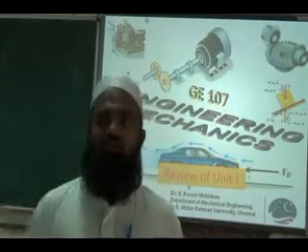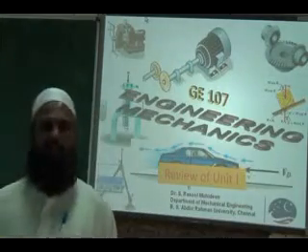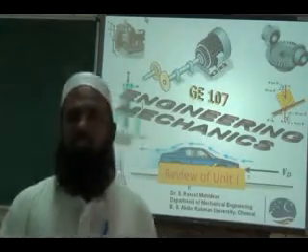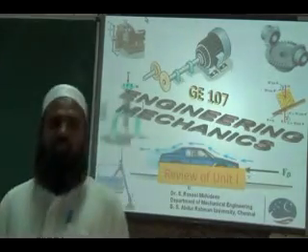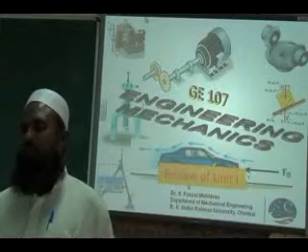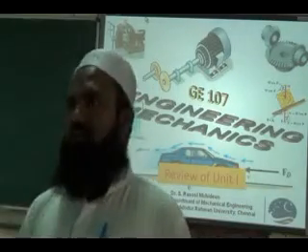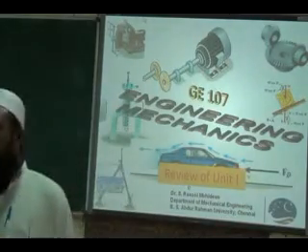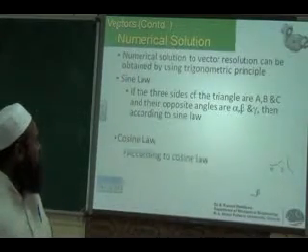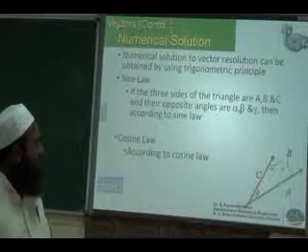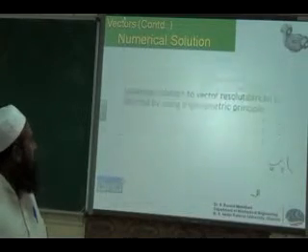In order to resolve the forces, there are many approaches. The parallelogram law and triangular law we solved graphically, and for the numerical approach we used the cosine rule and sine rule. If there are many forces, the parallelogram law becomes difficult to apply, so we have to use the Cartesian vector formulation, the unit vector concept. This portion we covered initially. The numerical solution is obtained by using the sine law and cosine law, and the graphical approach by parallelogram and triangular laws.